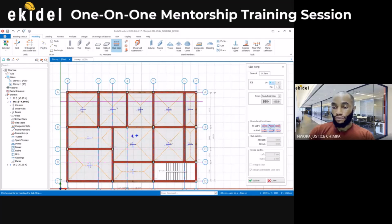So this middle one here, these are beam to beam boundary. They have at start and at end. If my boundary is beam to beam, I will choose this and this. This one here is if we have cantilever slab starting and cantilever slab ending. You can pick these options.